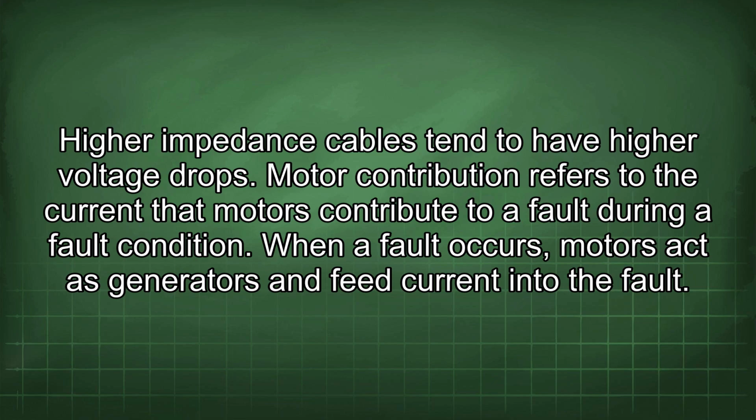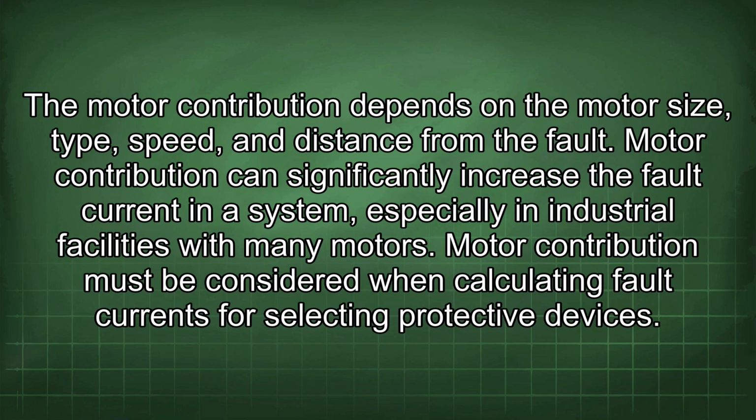Motor contribution refers to the current that motors contribute to a fault during a fault condition. When a fault occurs, motors act as generators and feed current into the fault. The motor contribution depends on the motor size, type, speed, and distance from the fault. Motor contribution can significantly increase the fault current in a system, especially in industrial facilities with many motors. Motor contribution must be considered when calculating fault currents for selecting protective devices.